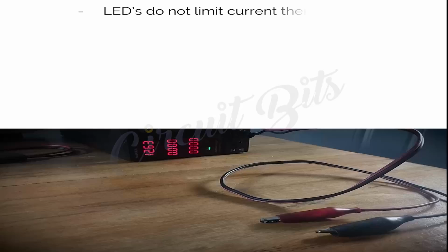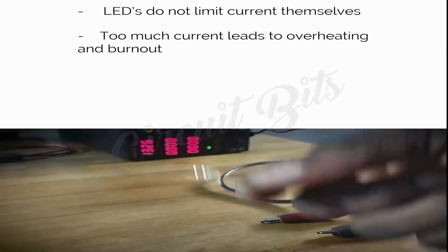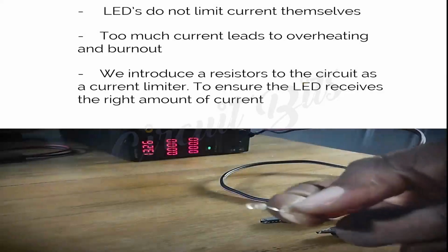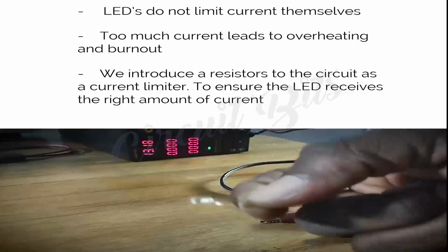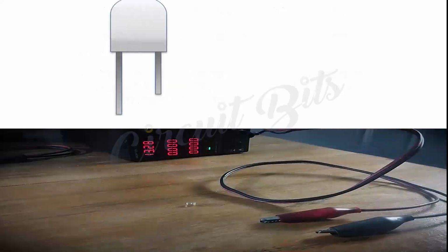Unlike regular bulbs, LEDs don't limit current by themselves. Too much current leads to overheating and burnout. So we have to introduce resistors to the circuits to limit currents and ensure the LEDs receive just the right amount of current that they need.